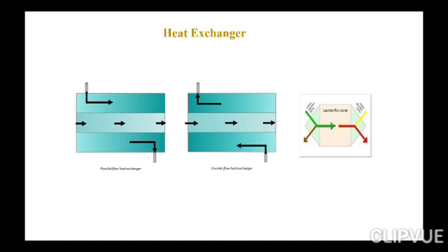Look at this picture. Both hot fluid and cold fluid flow in the same direction, each called parallel flow heat exchanger. Both the heating fluid and the evaporating fluid flow in opposite direction, each called counter flow heat exchanger. Both the heating fluid and heated fluid flow crosswise, each called cross flow heat exchanger.